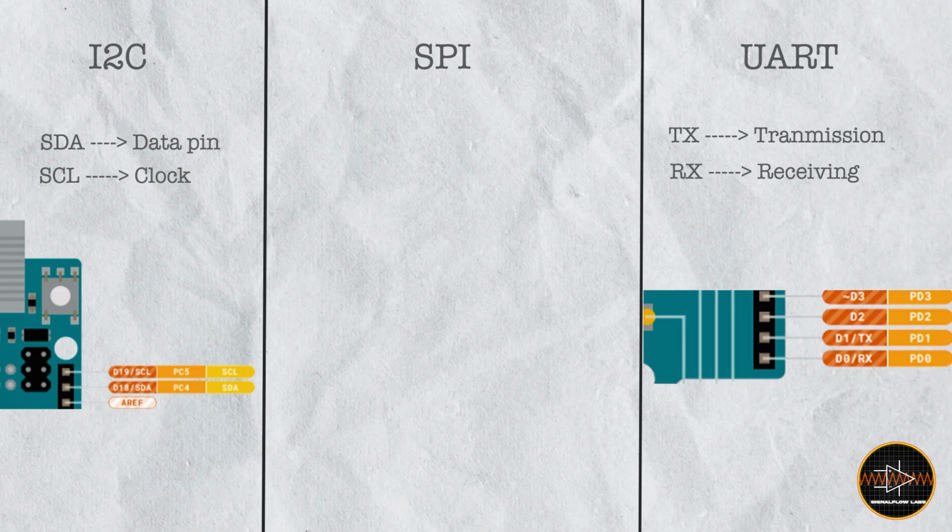So when you're dealing with a certain communication protocol in Arduino Uno or otherwise, you're going to make sure that all these pins that you have initialized or declared in the datasheet of that particular microcontroller, you have to use them only. If tomorrow I connect, let's say, pin 3 to TX and pin 4 to RX, it won't work basically. So we have to be assertive and firm that what we use is the dedicated pin. So before assigning pins based on your requirement of the project or anything, refer to datasheets and understand what the pin outputs are, so you can understand them better.